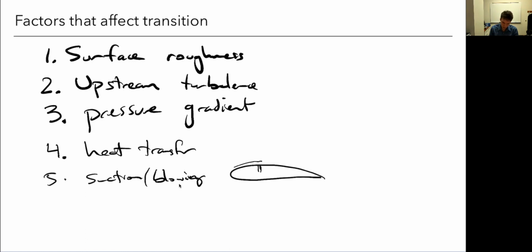Suction and blowing are similar ideas, where you might have a little port, right? And as the boundary layer develops, you could suck it in and a new one will develop. So we've delayed transition. Or we could have a port where we inject momentum into the fluid so that we may try to keep it attached longer, or to keep it in the laminar region longer.